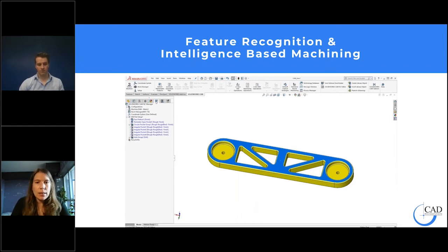We can use this command inside the software to automatically generate an operation plan or sequence of toolpaths for, let's say, one, multiple, or all of our machinable features. CAMWorks is going to scan the database that's running in the background, and it's going to apply our default strategies that we've chosen based on feature conditions. Things like the depth of feature, the width of feature, even things like the stock material or the spindle attribute. Is it a main or a sub spindle? It's going to scan these feature conditions, and then it's going to apply the toolpaths accordingly.